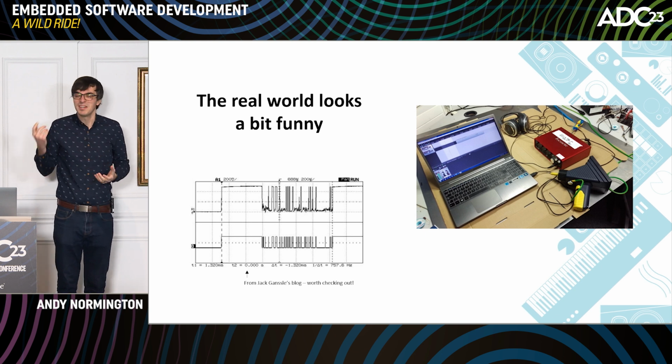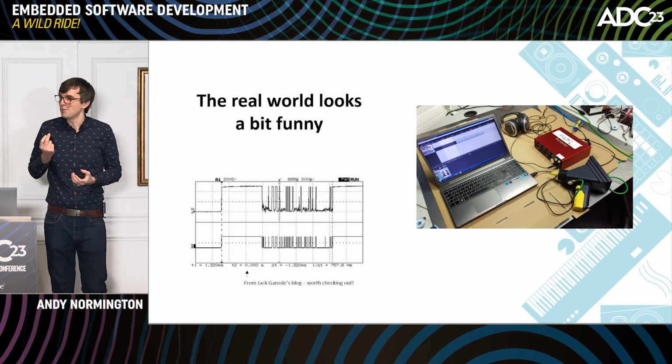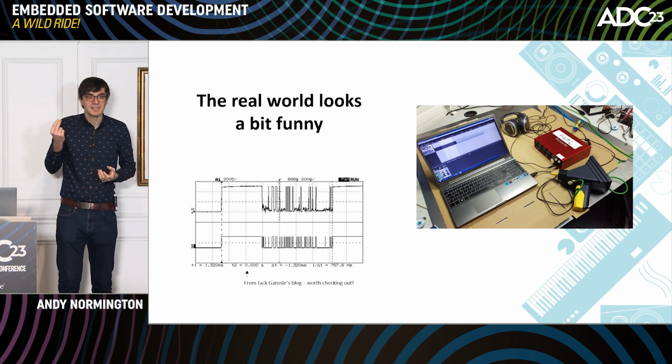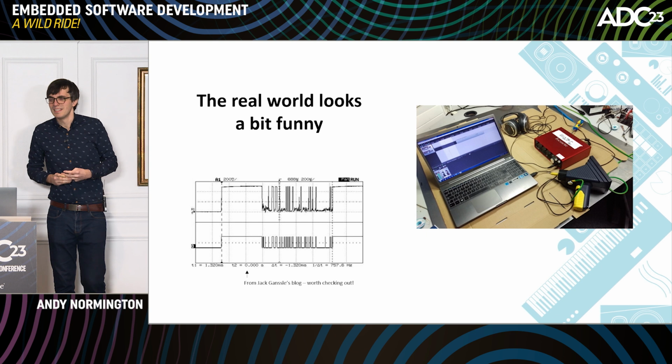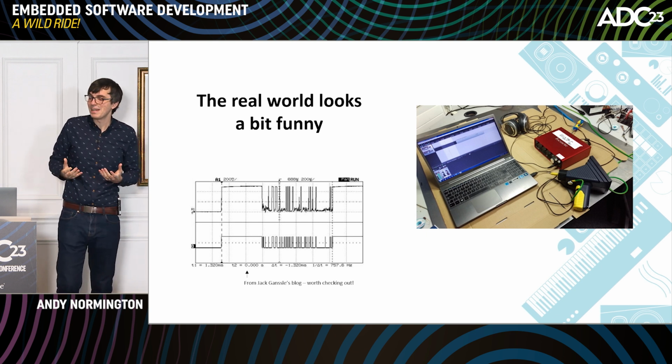It zaps across the PCB, and there's a voltage spike that comes up next to the microcontroller while it's turning on. Maybe it flips a bit in a peripheral register that we never expected to flip. Maybe it moves the program counter even. It can manifest in all kinds of weird ways. So we can't plan for it that much. We have to test for it.